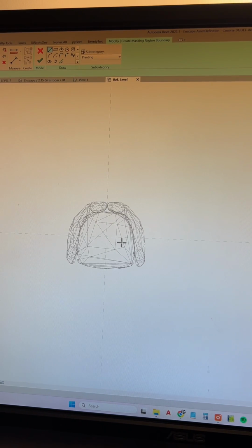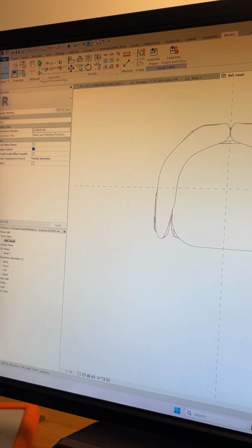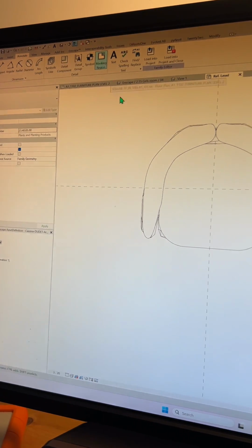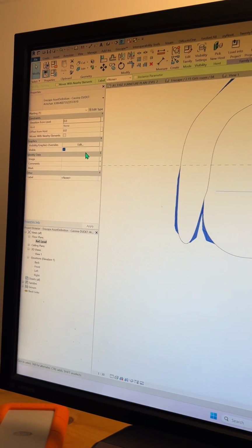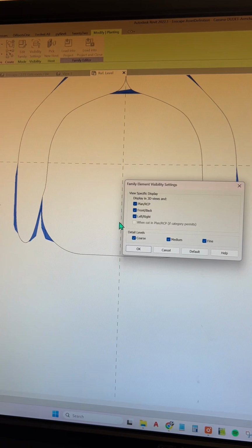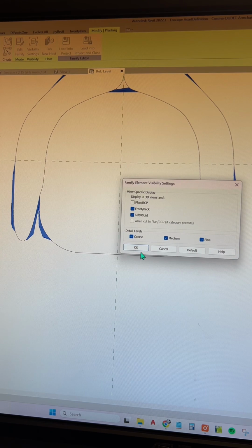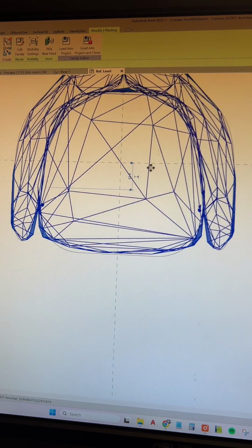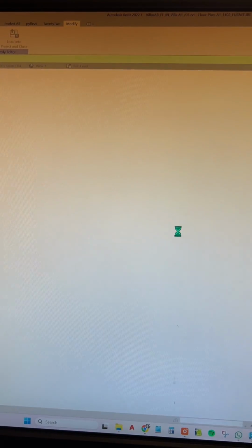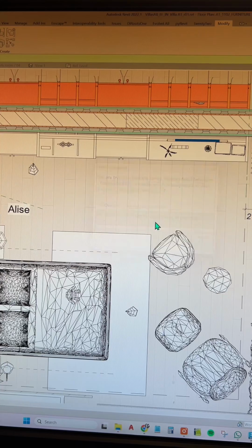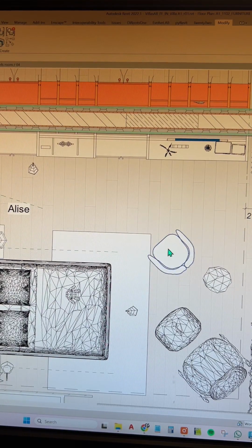I will now draw the mask. Firstly, I draw the mask using the annotate tool and going here to masking. And the last step I usually do is clicking on the geometry, going to visibility, clicking edit, and then unchecking visible in plan, because I don't want these lines visible in the plan. I just want to see my clean geometry. Then I load it into the project. I will not resave the asset, I will overwrite this one, and this will be the chair as it's going to be seen in my plans.